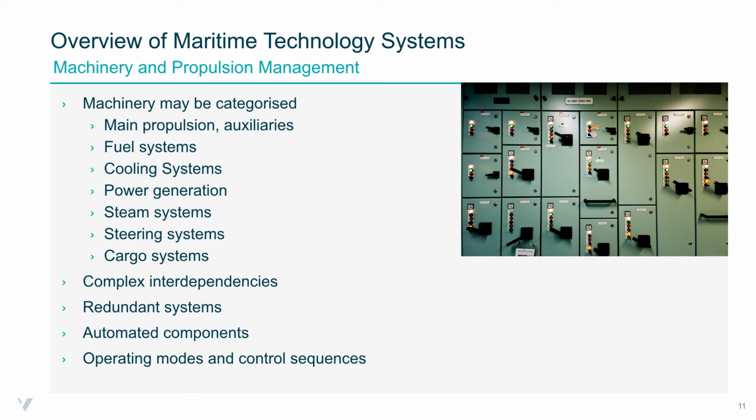In the case where there is an actuator, say, for a variable pitch propeller, the control system for the main engine will have awareness of the propeller pitch at any given setting, and it will provide feedback to the governors to provide fuel flow so that engine performance can be maintained at various propeller pitch settings.